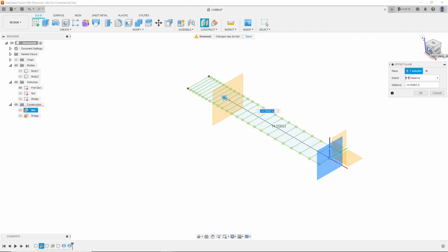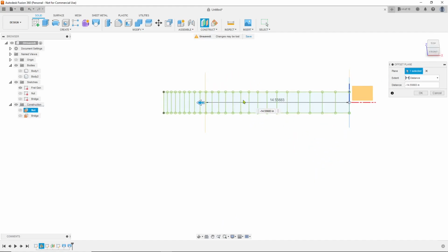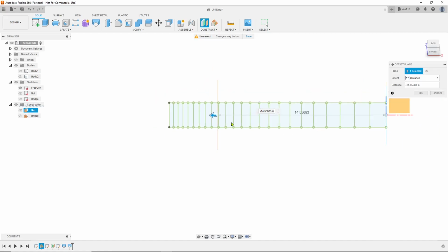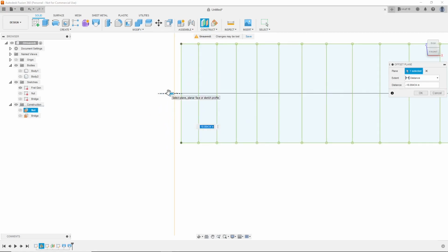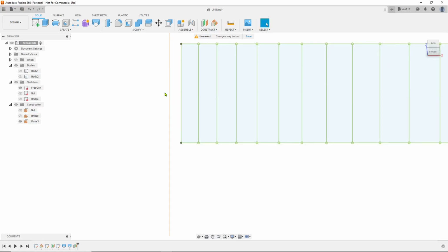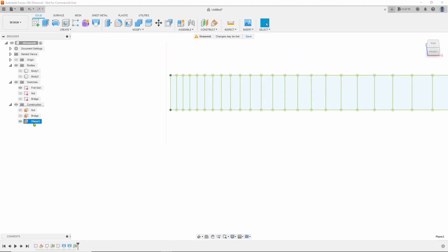I'm going to roll up on this 45-degree mark right here so I can see it better. And my negative direction will be just past my 24th fret back here, however much fretboard you want to see back here to your 25th position. So mine's going to be a negative 19 inches. Hit enter, I'm there. Now this plane I'm going to call the split plane.